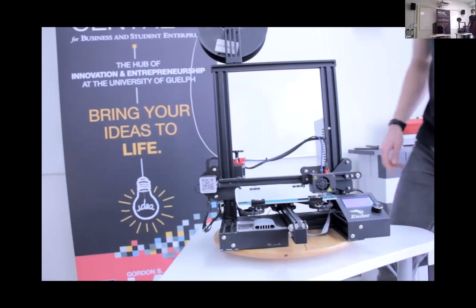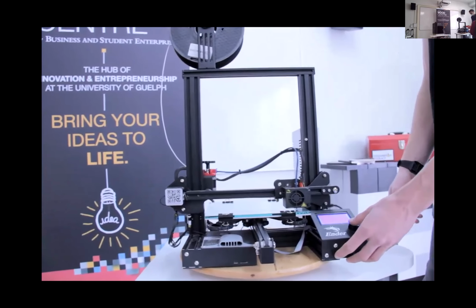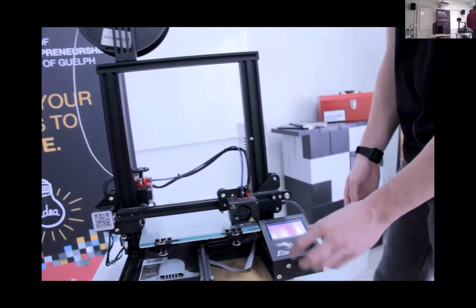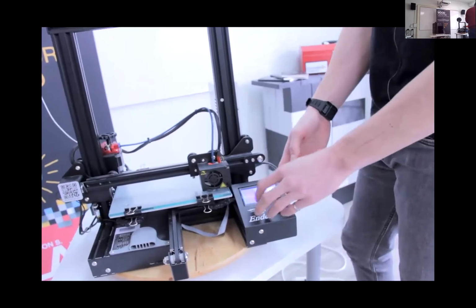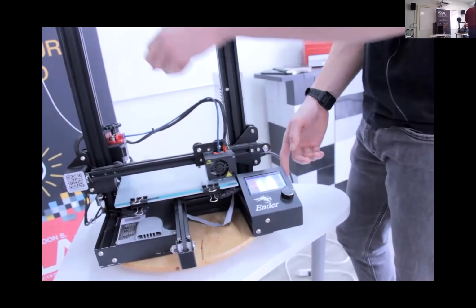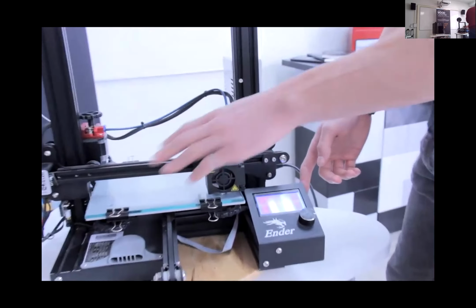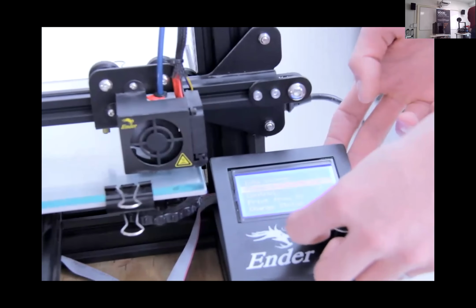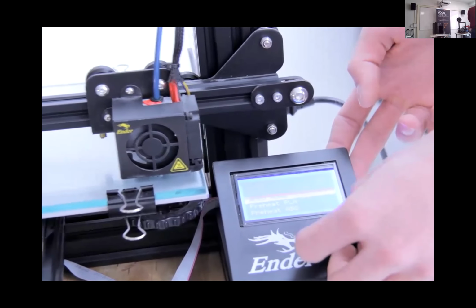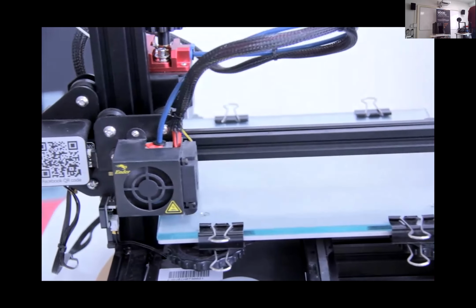This varies from printer to printer, and we'll talk about it on the Cubicon after. But the first thing you want to do is home your hot end. You can't do this if your hot end's up here somewhere. We want to make sure our hot end's as low as it can go and at its home position. So on the Ender 3, we just go to prepare and auto home. And the printer is going to bring the hot end to its home position.